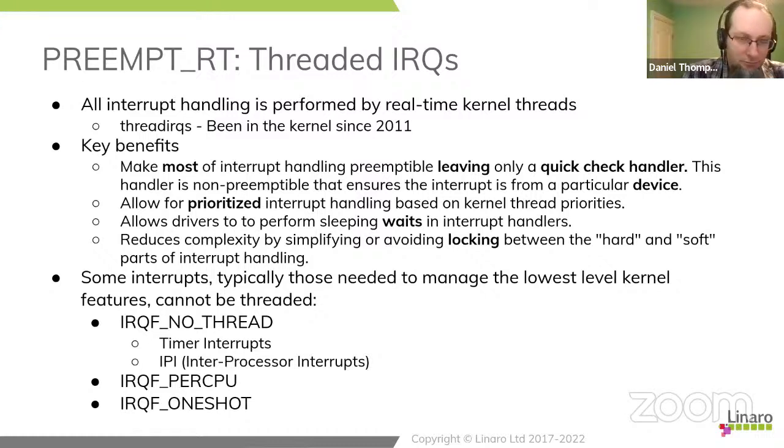And the basic idea is that you split the interrupt handler into a quick check handler and the bulk of the handler. The quick check handler's only job is to verify that the interrupt is actually pending. And if the interrupt is pending, make some action to stop the flag being raised to the CPU. So we find a way to mask the interrupt somewhere, and then we exit. That's the quick check handler. And then we call a second half handler, which actually does the interrupt handling. It studies things, it makes the change, it changes the hardware.